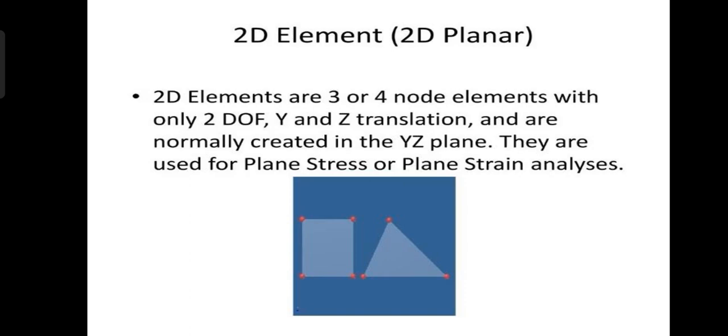2D element, that is the 2D planar. 2D elements are 3 or 4 node elements with only 2 DOF, Y and Z translation, and are normally created in the YZ plane. They are used for plane stress or plane strain analysis.